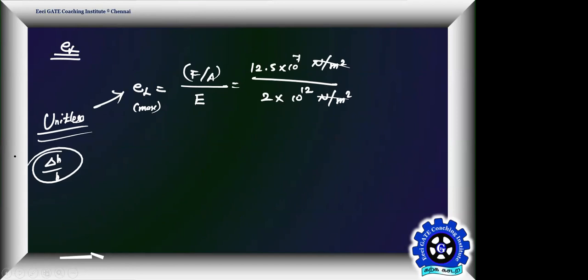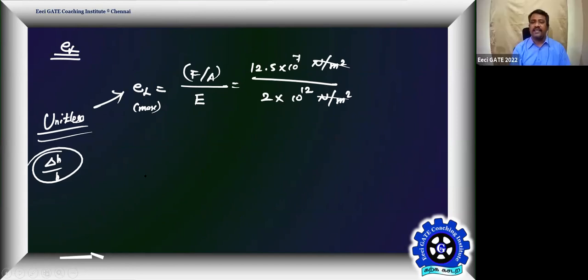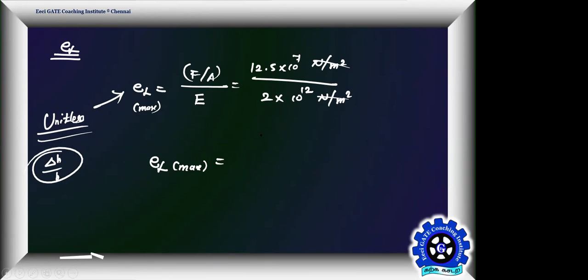Yes, that's your unitless strain in the load cell. That's the maximum strain your load cell can offer for this maximum loading condition. This loading is different. This is completely mechanical loading, not electrical loading. Electrical loading is drawing some current from the source, and this is mechanical loading, purely applying a load on a metal block. Getting it? Yes, sir. Now tell me what is the number?